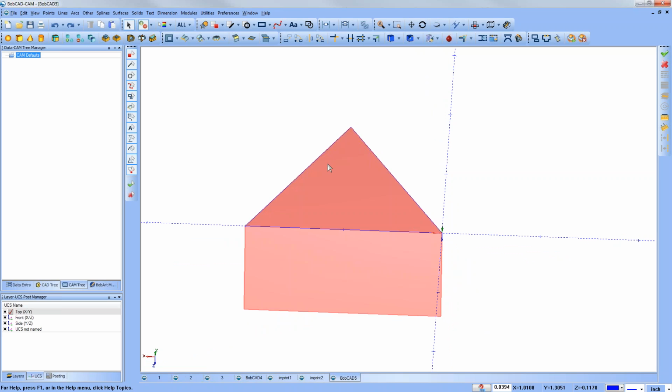I'd create a smaller triangle and then extrude cut at a taper angle. If that didn't do quite what it needed to, or the shape doesn't lend itself to that, you may have to, in some cases, create wireframe geometry and then maybe do a Boolean subtract. So the tools are there. It just depends on the part.